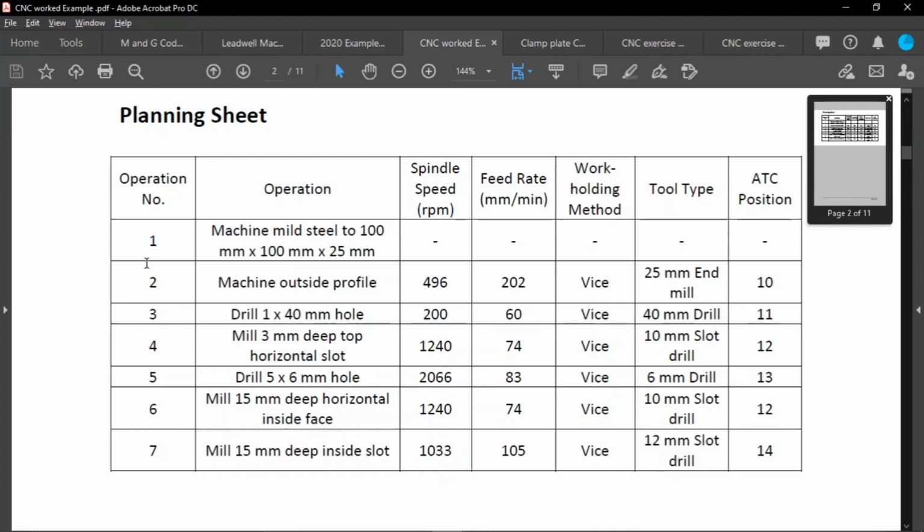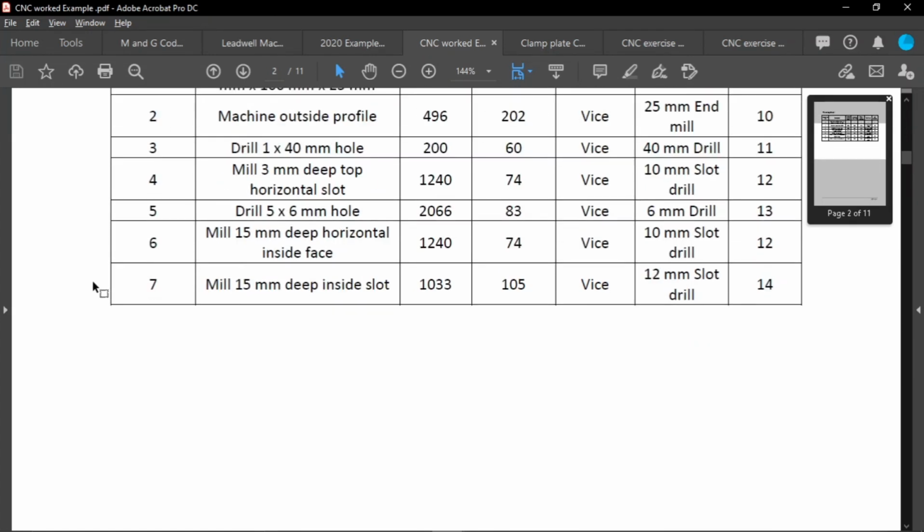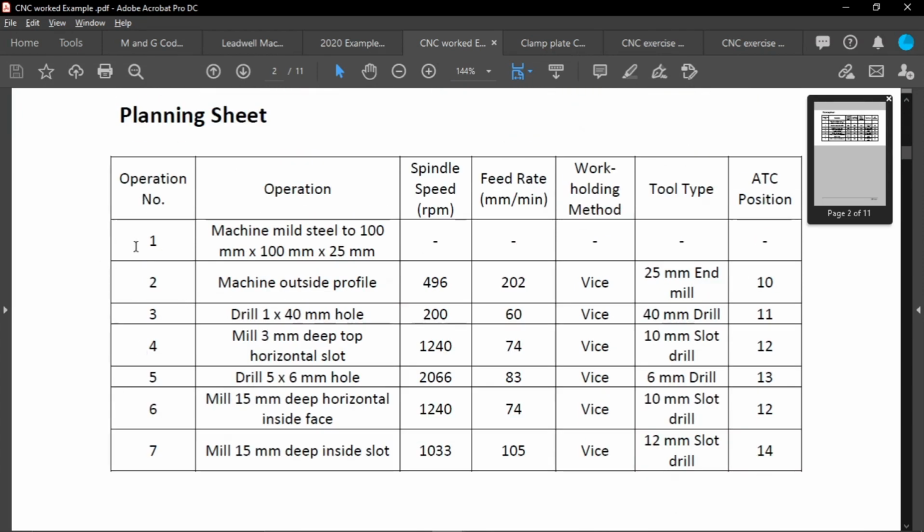Before drilling as well, there's a particular process that needs to be done, which is called spot drilling. That is to have some spots or punches at the drilling places so that the drill won't slip to either side, right? So basically this is the operation schedule, right?